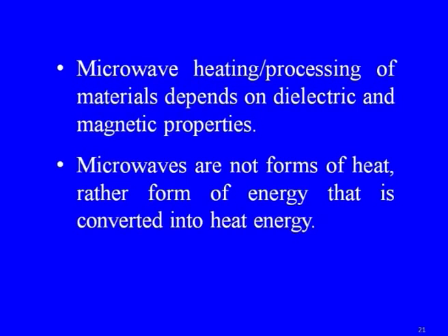In the case of some polymers, curing gets enhanced because of exposure to the microwave energy. Therefore, in these cases we can say it does not necessarily result in heating, but we can very well term it as processing. Microwaves are not a form of heat, but rather a form of energy that is converted into heat energy. This is a very important concept.